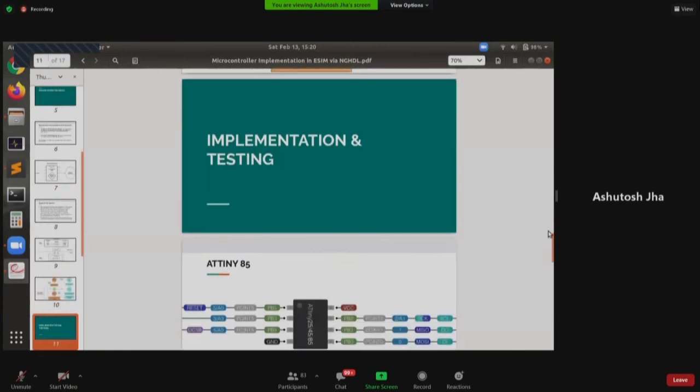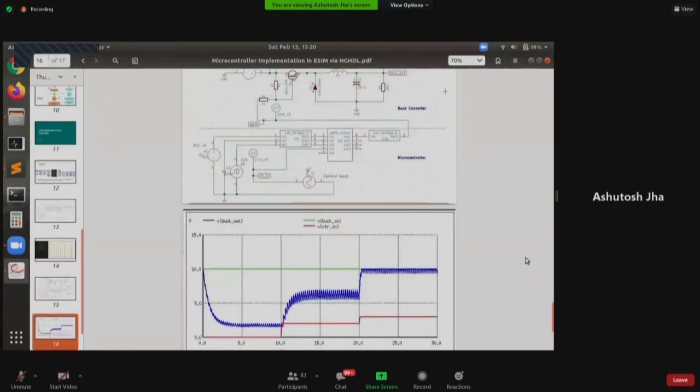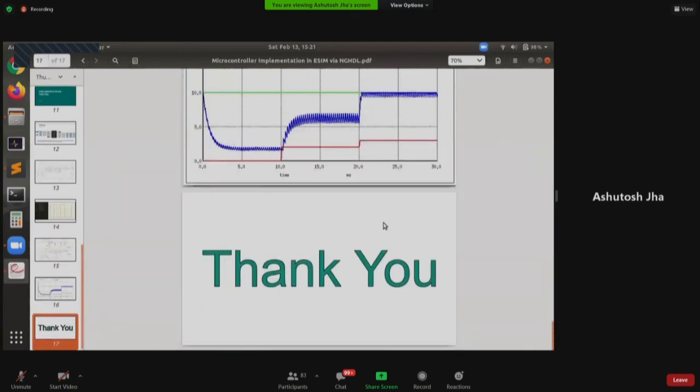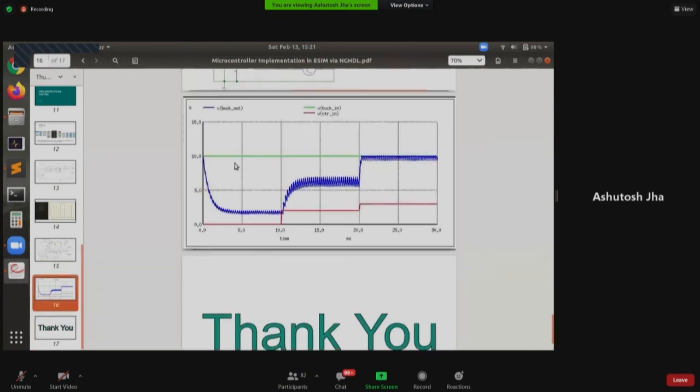So what has been done as of now, for the AVR microcontroller family, we have implemented all the instructions. There are around 125 to 150 instructions that we have completed, me along with a few more interns, and we have implemented timers. I think the work on interrupts is going on. So interrupts and the analog input, basically analog to digital conversion, that part is left, and interrupt part is left.